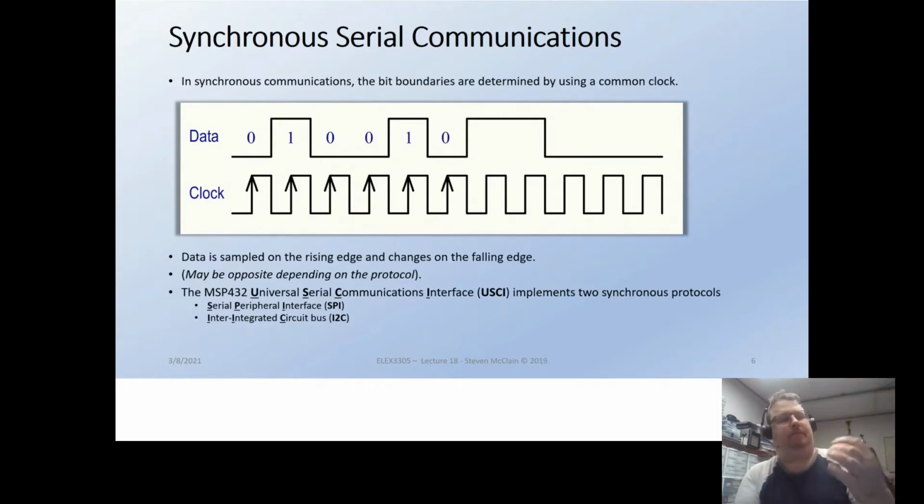That's a 16-bit A to D converter that hooks up with I2C communication. So I can hook the MSP432 up to this, and I get a 16-bit A to D converter, or a bag of them.